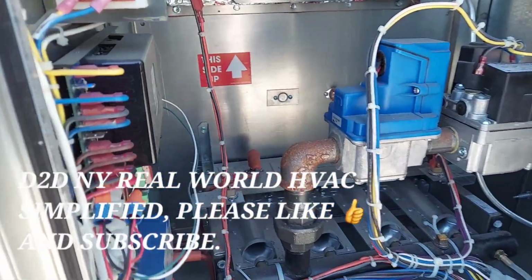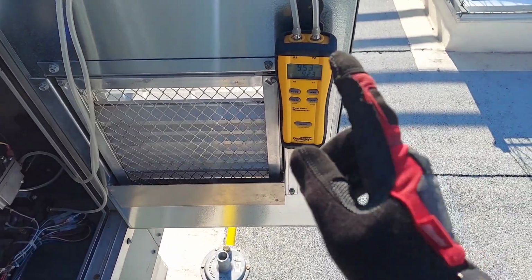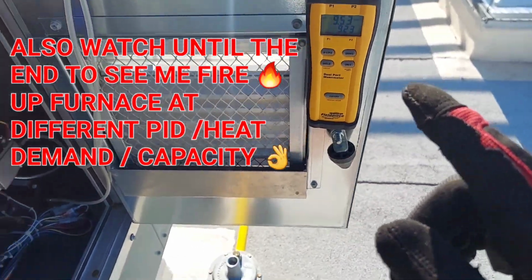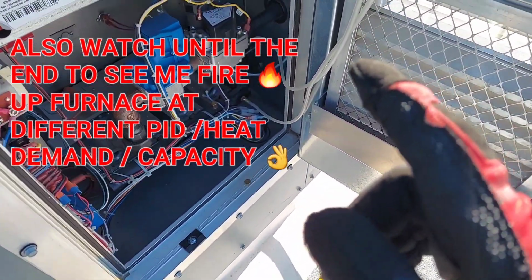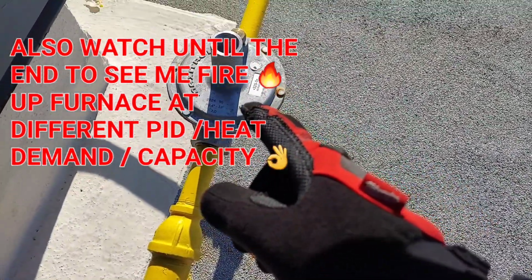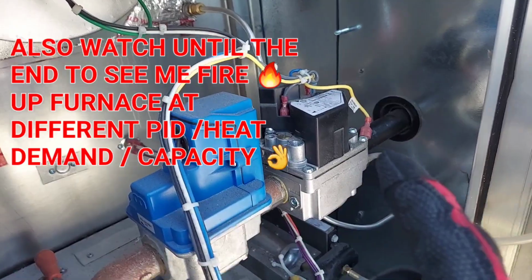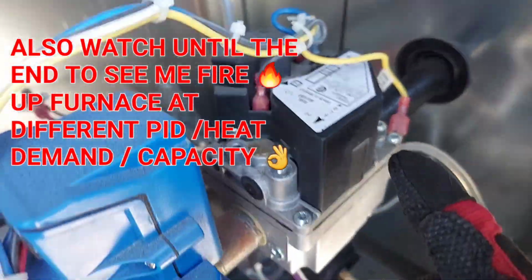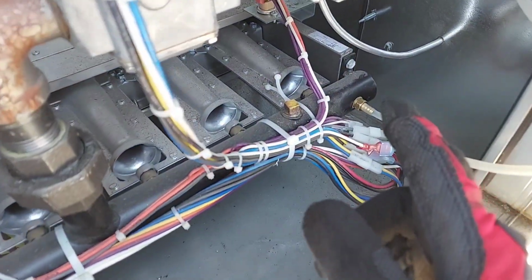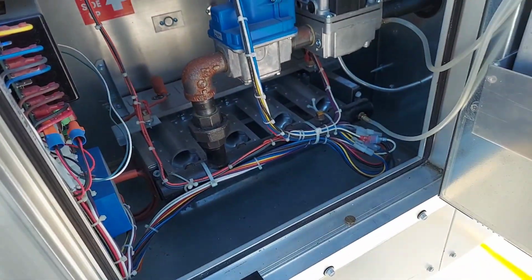And now in this video I'm going to be showing you how to use your manometer to check your inlet gas pressure, adjust your inlet pressure regulating valve, or PRV, and also adjust your gas valve so that you can have the right operating pressures on the manifold or the burners. All right, so that's happening in this video.